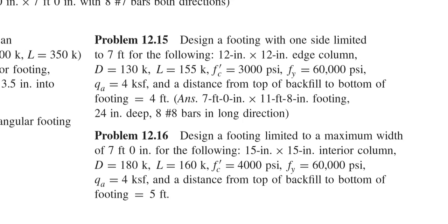This time I will discuss a rectangular footing design. Problem 12.15 in your book says: design a footing with one side limited to 7 feet for the following. 12 by 12 edge column. Edge means like at the boundary of the plan.